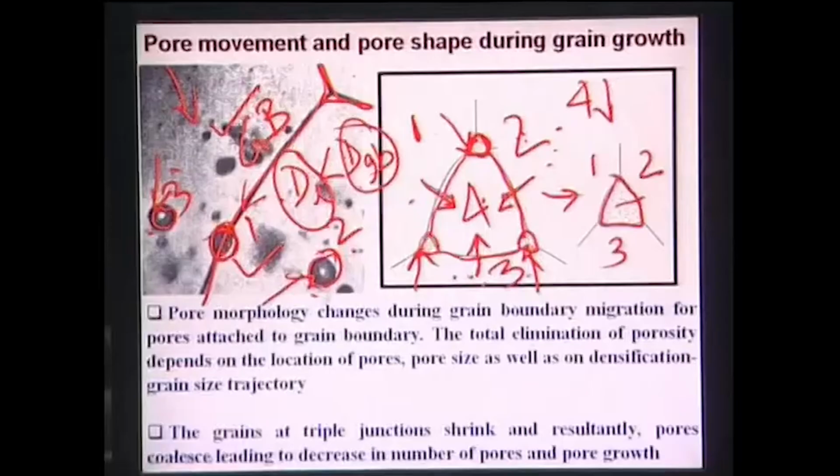So those pores will remain, because your lattice diffusion is always slower compared to your grain boundary diffusion. So from these considerations, it should be very clear to you that you do not want your pore separation to take place at any point or at any stage during the sintering process.